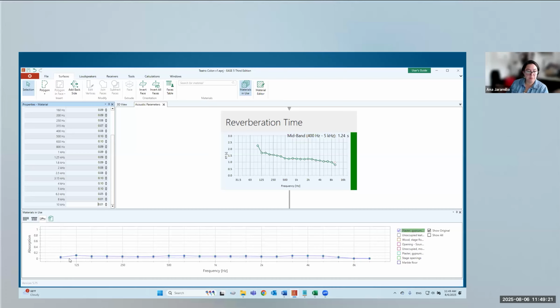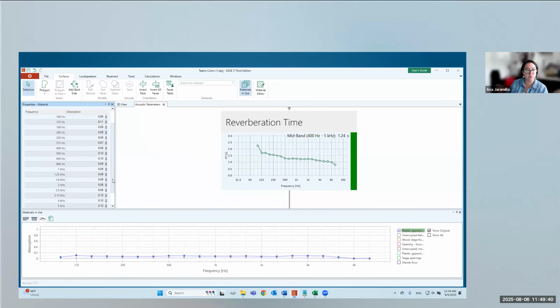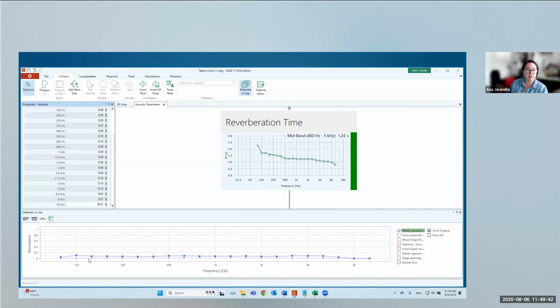At this point, the question would be, is that fitted line that I created reasonable? So is it reasonable to think that a plaster might absorb that much? So I went from 0.02 to 0.07, 0.08. And I think in this case, for this material, it's still reasonable. So I'm not assuming plaster is 0.4 just to be able to match it.